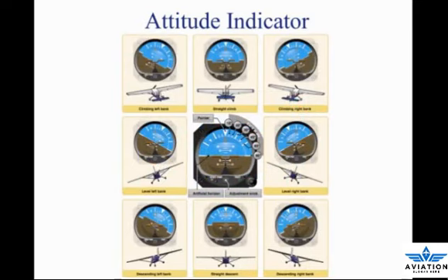Every pilot should be able to interpret the banking scale illustrated above. Most banking scale indicators on the top of the instrument move in the same direction from that in which the aircraft is actually banked. The relationship of the miniature aircraft to the horizon bar should be used for an indication of the direction of bank. The attitude indicator is reliable and the most realistic flight instrument on the instrument panel. Its indications are very close approximations of the actual attitude of the aircraft.